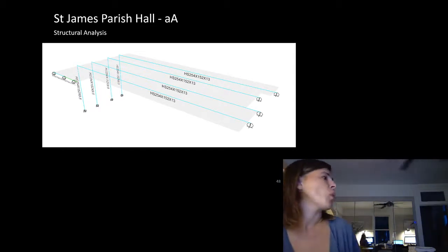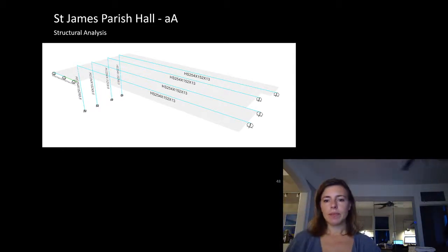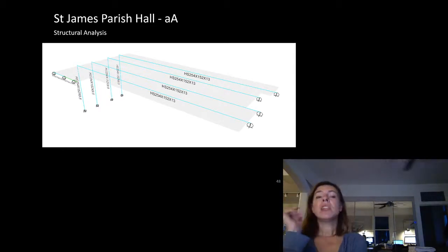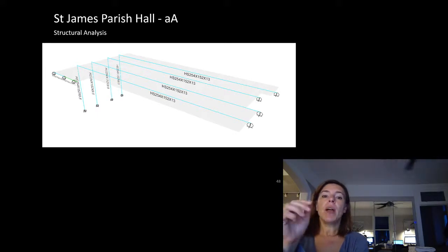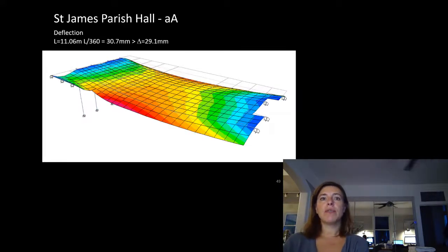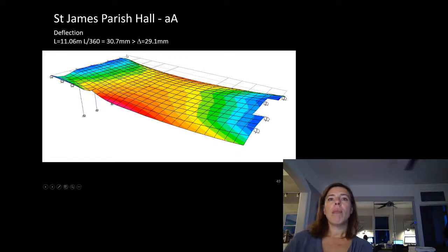I have the one blower canopy. The deflection, you can see here's the deflection diagram. I actually did the calculation to show you that the worst case deflection of the member was 11 millimeters. And this is a nice flat thing, where you would really read that. And we actually talked about even a tighter deflection criteria, and we worked through this with the architect.